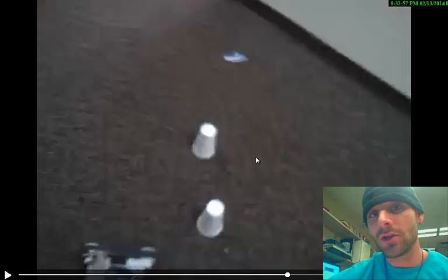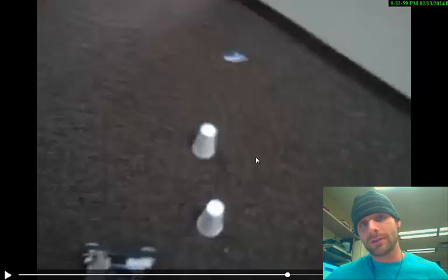So every step, if I'm off 3 degrees one step and off 3 degrees the next step, as time goes on, it begins to compound, and my real location based on my computed location is very inaccurate. So dead reckoning becomes an issue over time because of noise in your sensors, and that's something I have to deal with. Not quite sure how I'm going to deal with that yet.